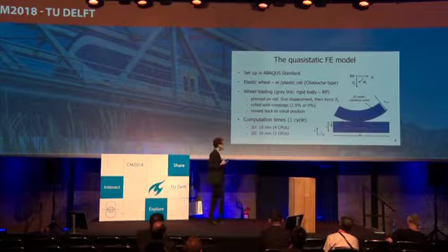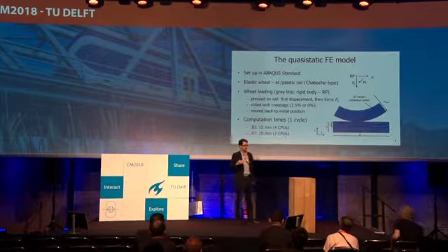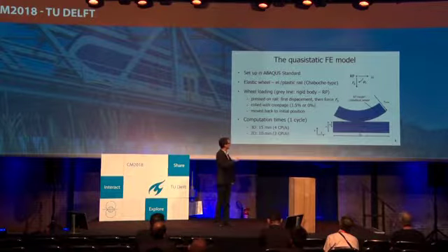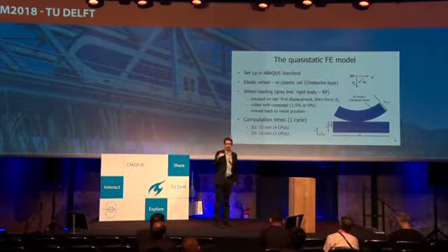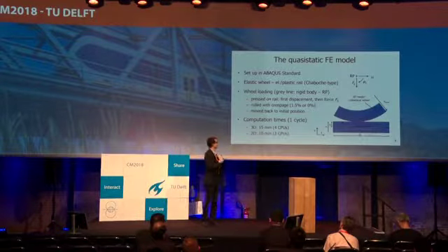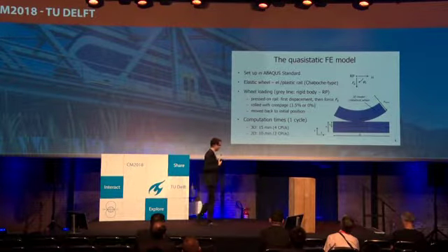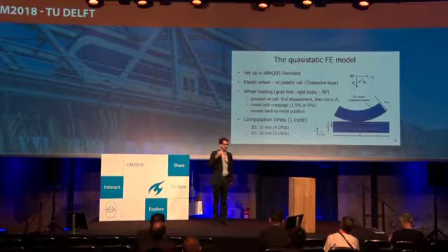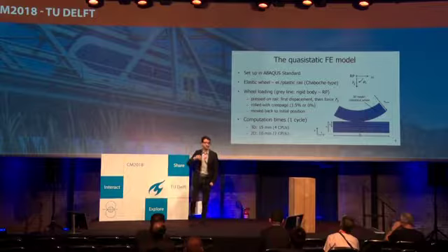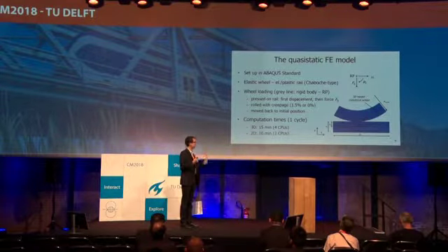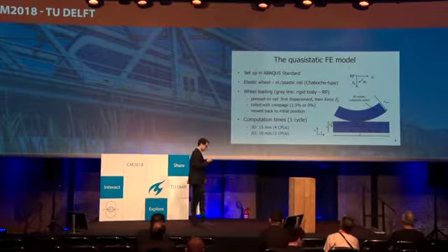What you don't see here is the 3D model. It could be really 3D, and at that point, we investigate loads where we have a conical wheel. While we're doing that, the voestalpine test rig can be set up to have a cylindrical wheel, which is rolling on the rail head. And then they can apply a slip, for example, 1.5% in an accelerating movement, and then they actually already measured plastic shear deformations for, I think, 700 cycles, 1,400 cycles, and many more cycles. So that would be our means of validating that. We're not showing stuff on that because we have to define all the details about the test, but that's where we're heading.